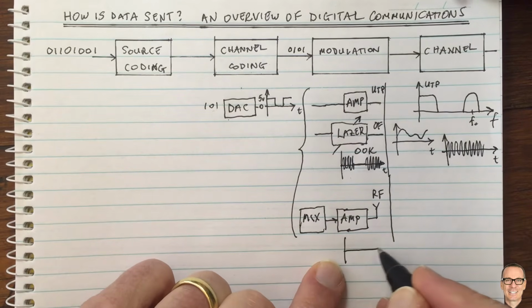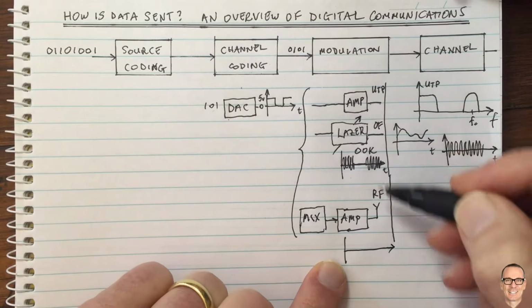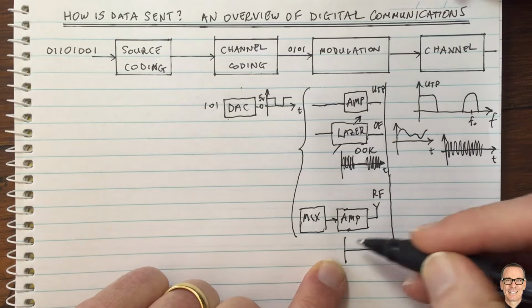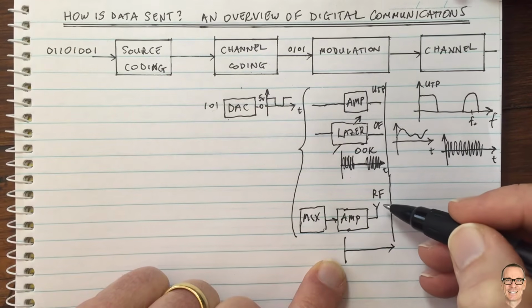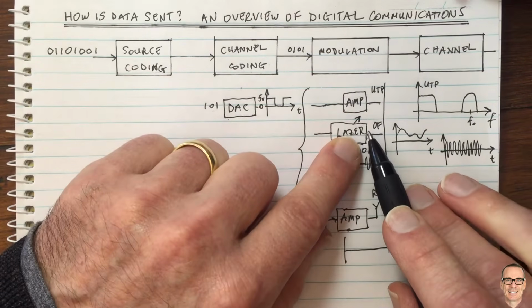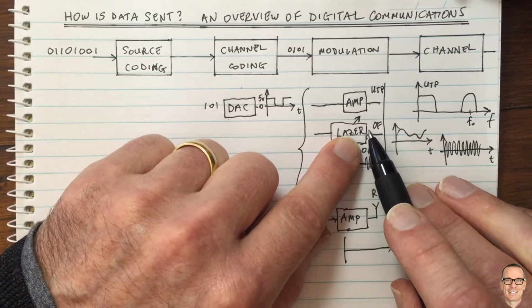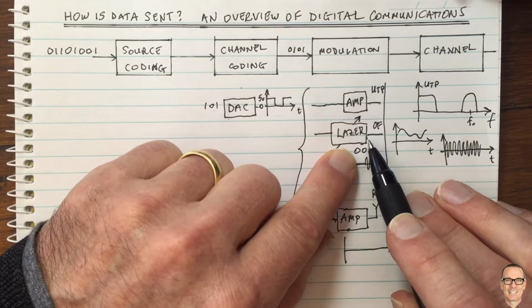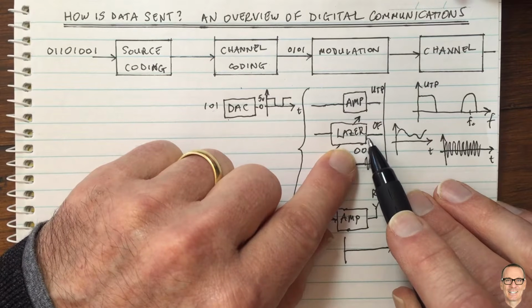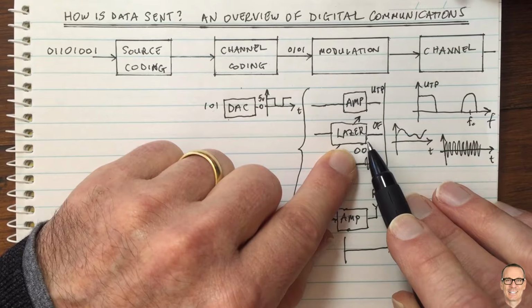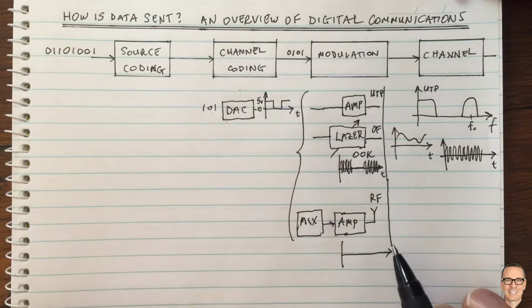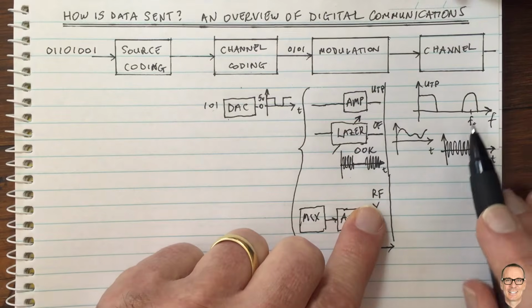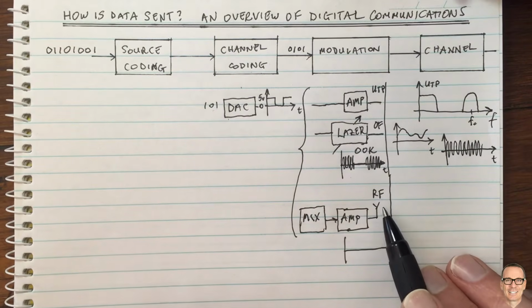course. Let me just go one example further here for this waveform. So instead of on-off keying, we often use something which involves the phase when we've got radio frequency, because our receivers can receive the phase accurately. Whereas for optical fibers, the receivers that we have generally, or the ones which are able to be put into commercial grade consumer products, can't estimate the phase of the light. But you can estimate the phase of the radio frequency. It's a lower frequency, and we have receivers that can estimate the phase.